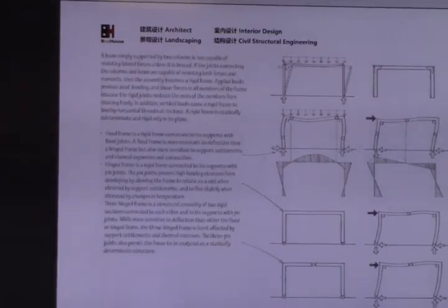This is a rigid frame. That's what we were talking about with the moment connection here. Because it's a rigid frame, the deformation is different, because they have moment connections everywhere. So they can resist more horizontal force. So we use the rigid frame to resist the horizontal force.